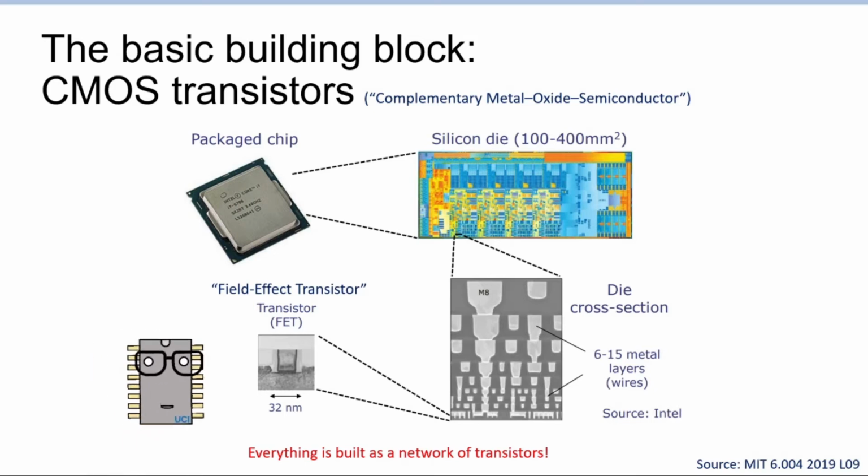And this is different from 3D stacked silicon technologies, if you're familiar with something like that. The things that are stacked on top of the transistor layers here aren't other silicon layers. Well, they're silicon, but they're not the transistor layers that we are talking about when we talk about 3D stacked architectures. When we do 3D stacked architectures, they talk about when we have more than one layer of these transistor layers, which is more difficult to do.